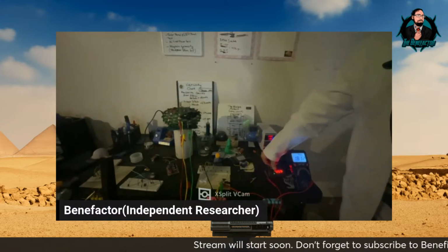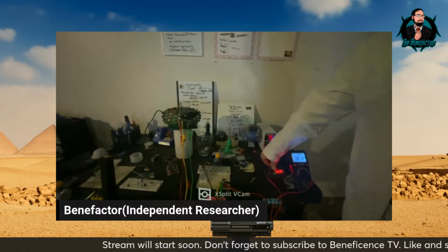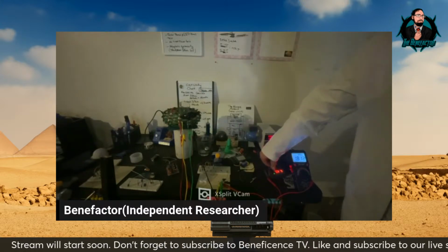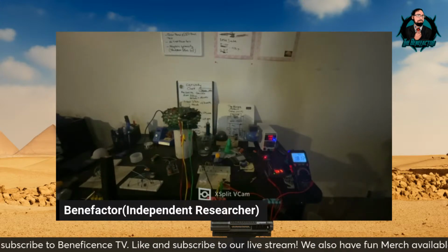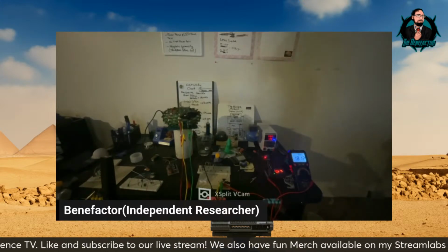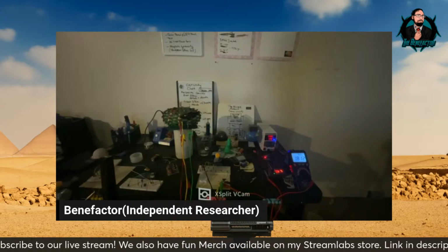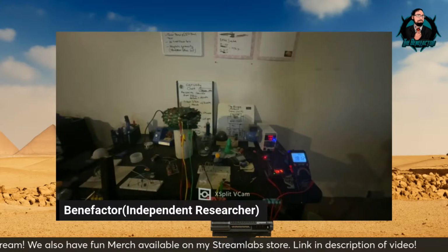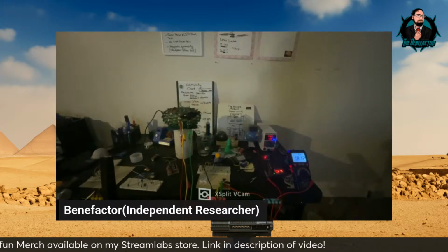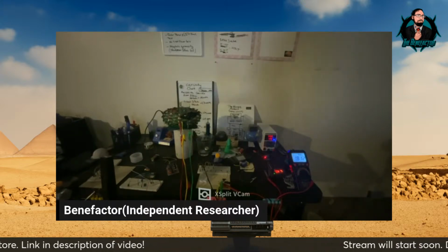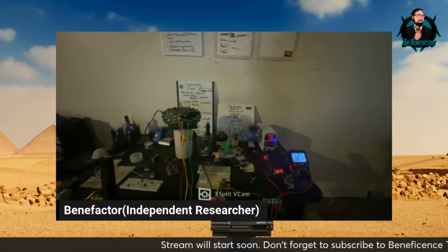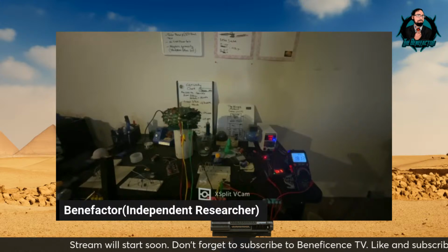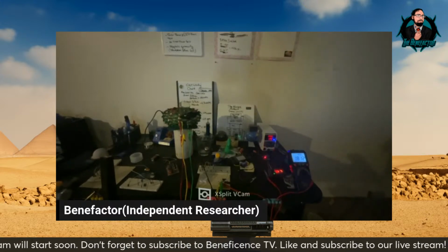I think your hertz may be way off, Ben. You may be way too high. I think we need it a lot lower, because the only time I've ever seen this coil produce that electromagnetic field is with DC. You need to hold the contact down longer for the voltage to get across the coil, so it needs a longer duty cycle. And it also needs a lower frequency. We can hook it up to the signal generator, and I have the Arduino circuit in a minute to see what happens.